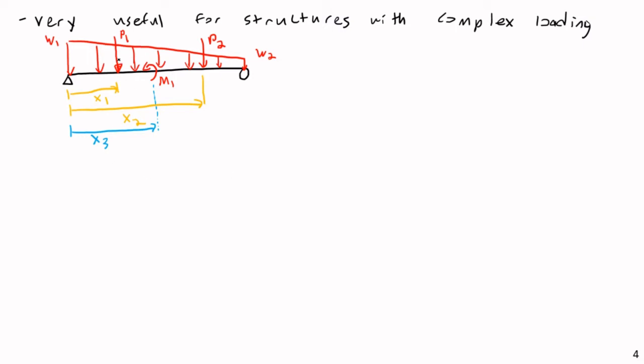Well, I'm looking at this, and I think I'm going to break this down into 5 sub-beams. Let's say I'm interested in finding the deflection. Let's say I want to know what is delta as a function of x for this whole beam. Well, what I could do is say this is actually equivalent to the summation of 5 different beams. Let me draw this with 5 different beams.